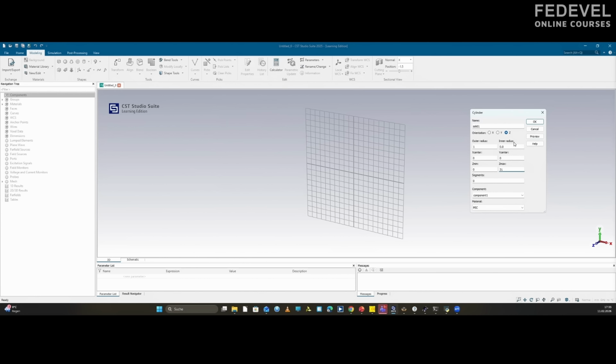You can remember 30 gigahertz per centimeters: if you divide it by the working frequency, and 2.45 gigahertz is the mid frequency of Wi-Fi, you have 12 centimeters of wavelength, and the quarter of it is 30 millimeters, or 31. And so you see here the rod.